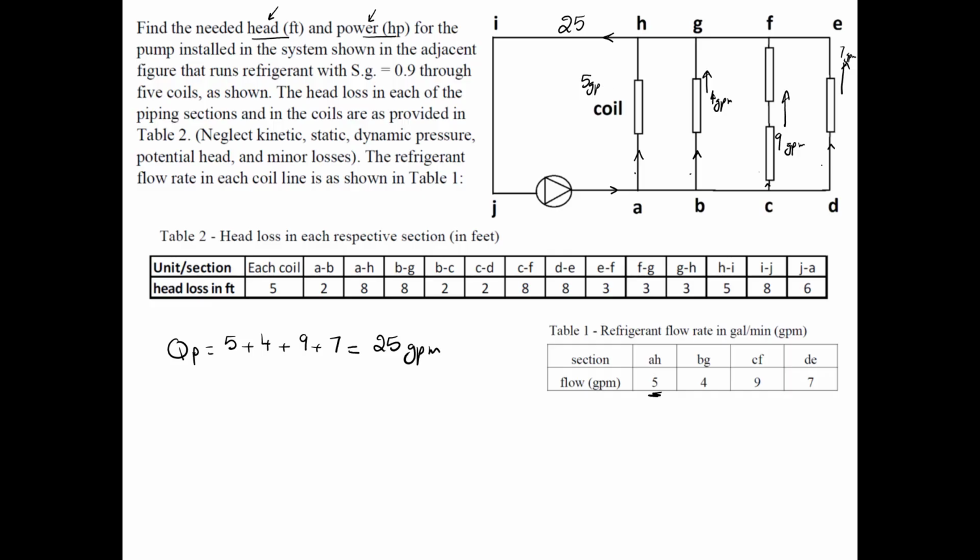Now, I'm going to just remove these. So don't jump into the assumption that the head loss at the first one equals the head loss across DG, equals the head loss across CF, equals the head loss in DE. Actually, this is head loss, and these are pipes here, so we need also to consider these lines. So in fact, to solve this correctly, we have to look into the overall path.